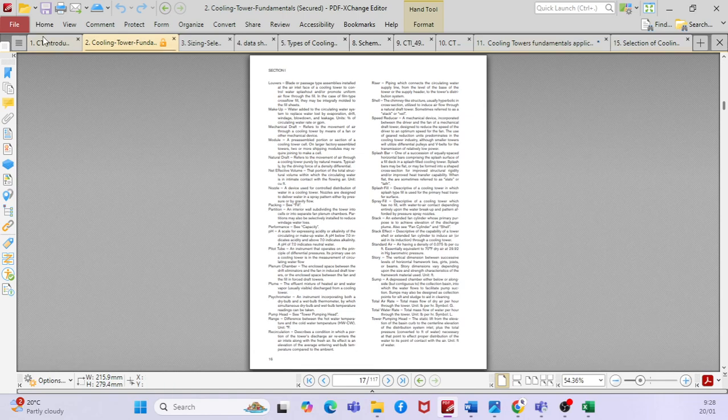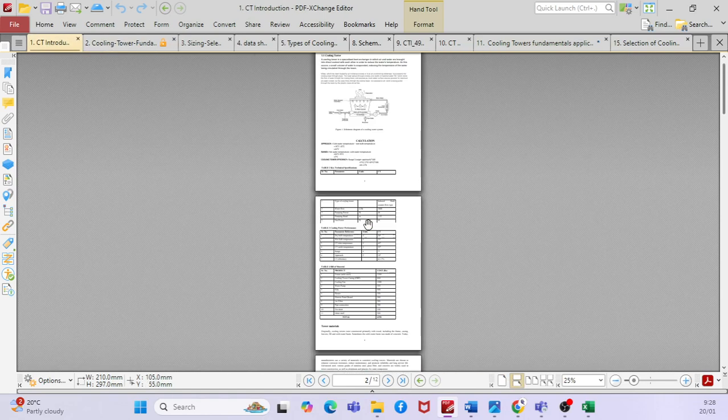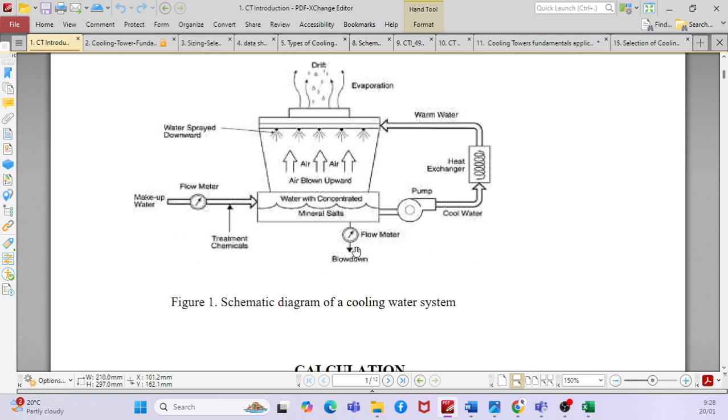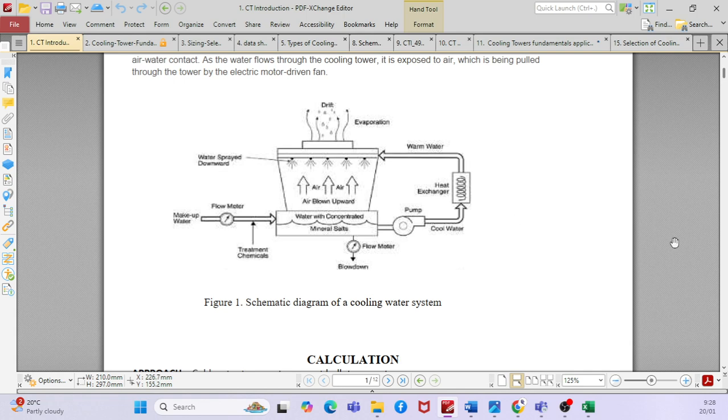But how many of these cooling towers have we actually used in projects? Have you used all the cooling towers that you've shown right now? Basically, in our building projects, we normally use forced ventilation because when you use natural ventilation, you need a large size of the vessel. The cooling tower itself will be big. The tower is a very big one because it's a natural ventilation, right?